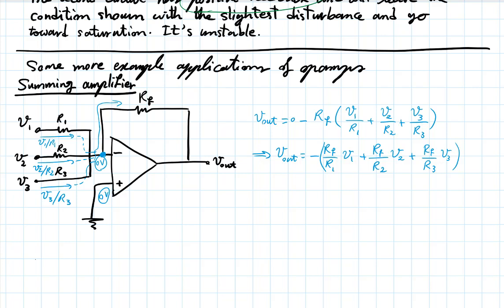So let's say you have 3 bits, zeros and ones, in a circuit maybe represented by 0 volts and 5 volts for 0 and 1, and then converts it to an analog signal. Yeah, exactly. So you're saying have the proper ratios here so that they give you the proper weight factors between your various bits or digits based on their significance, right?